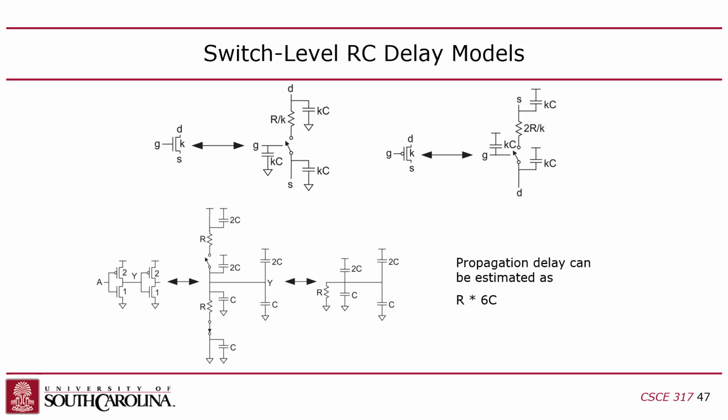Now you might say, well, wait a minute. How do you calculate that in terms of seconds? So if you substitute in R and C values, you get seconds. This is literally seconds. The units are seconds. The capacitance, of course, would be farads. And you can get that. That's literally part of the technology parameters for your process. The resistance, though, is a little harder to come by.